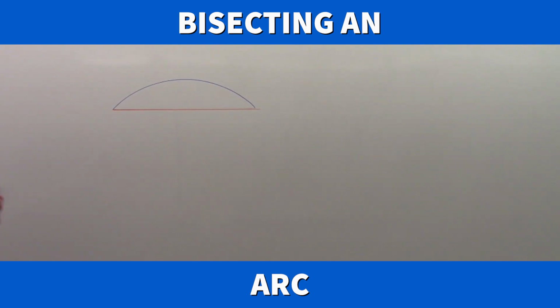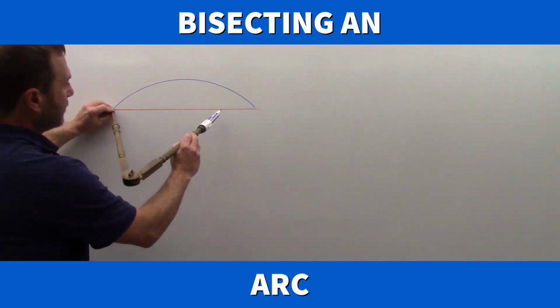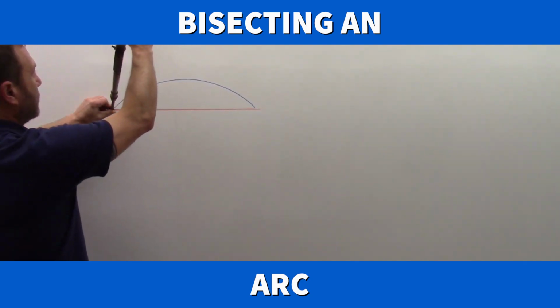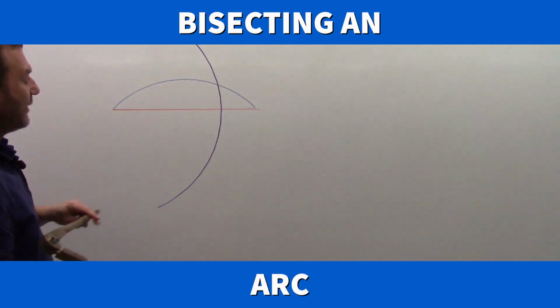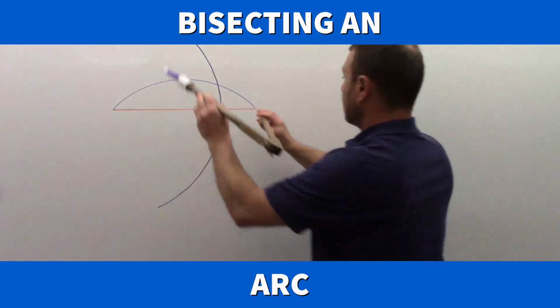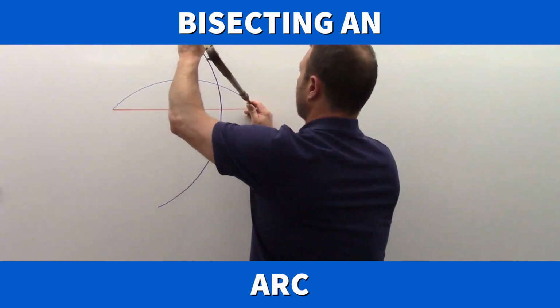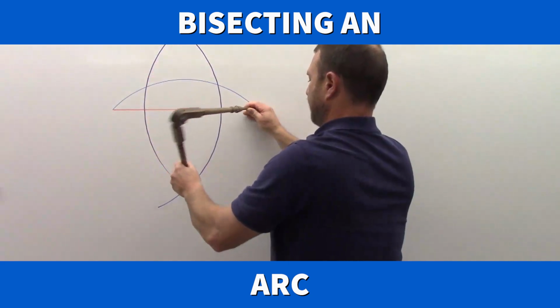So we take our compass, we set it to approximately 3/4, and I swing an arc from one side, and keeping the same distance on my compass is very important. I swing an arc from the other side.